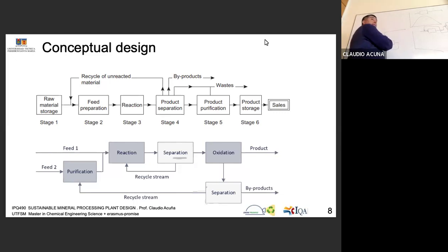So first you classify, because only the coarse particles go to the ball mill. This is in the cleaner section. Do you remember the circuits? Okay. If you don't, it's not that complex. It's a reverse, because you classify first and then have a particle size reduction.